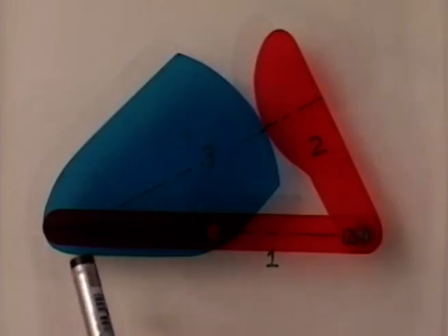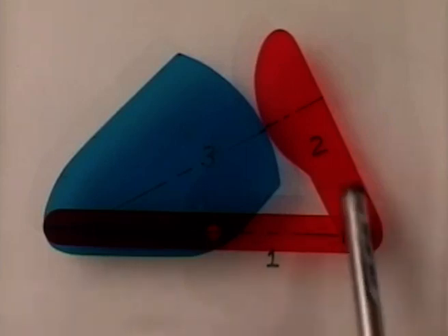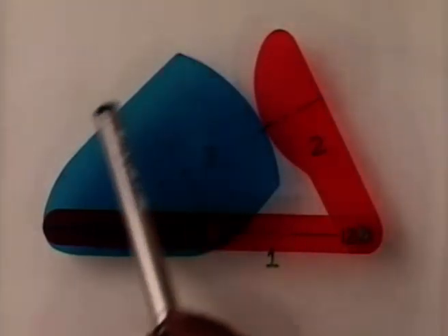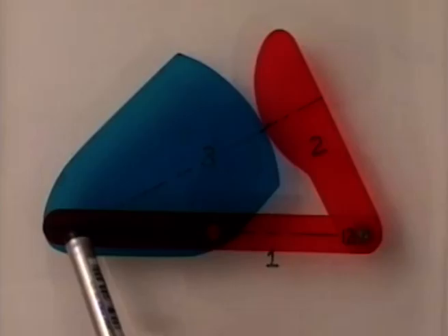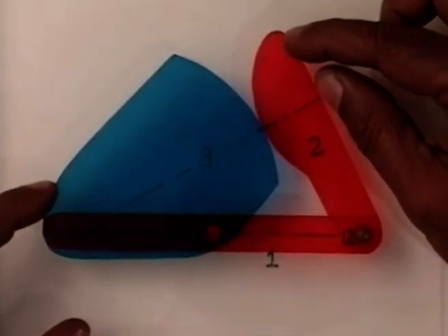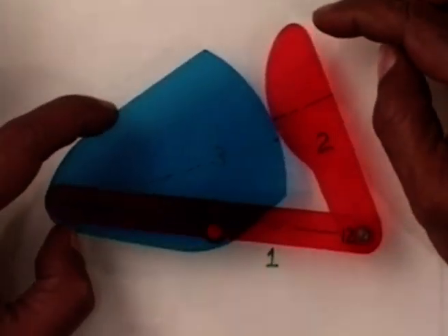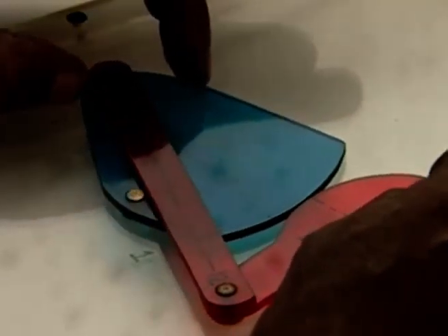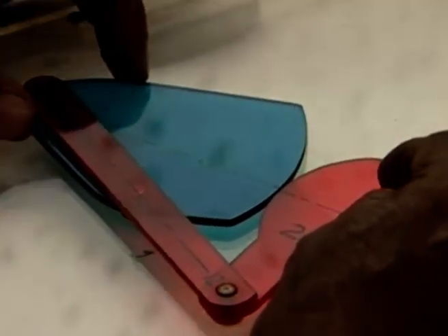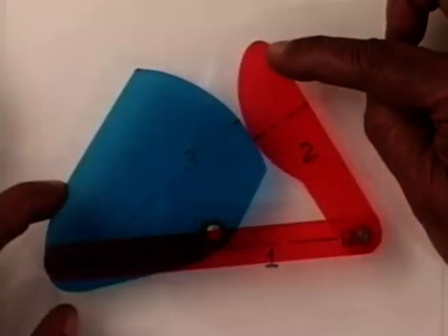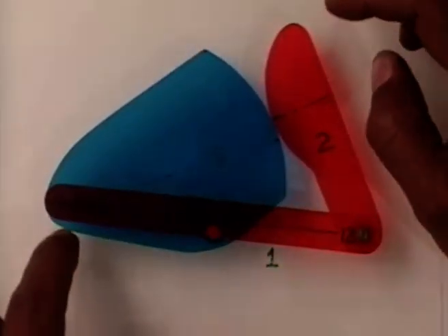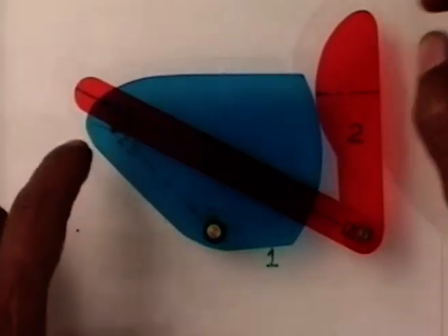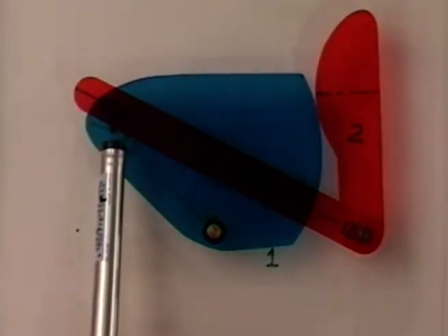By definition, at this instant, if I consider this point to be a point on body 2, that is this red link, or a point on body 3, that is this blue link, they have the same velocity. So as we will notice, around this configuration, these 2 points on body 2 and body 3 at the location of I2,3 move with the same velocity. However, these 2 points now, as we see, have moved differently.